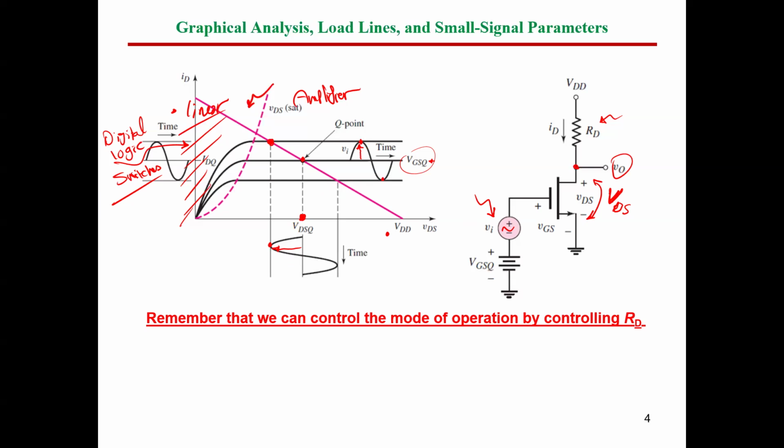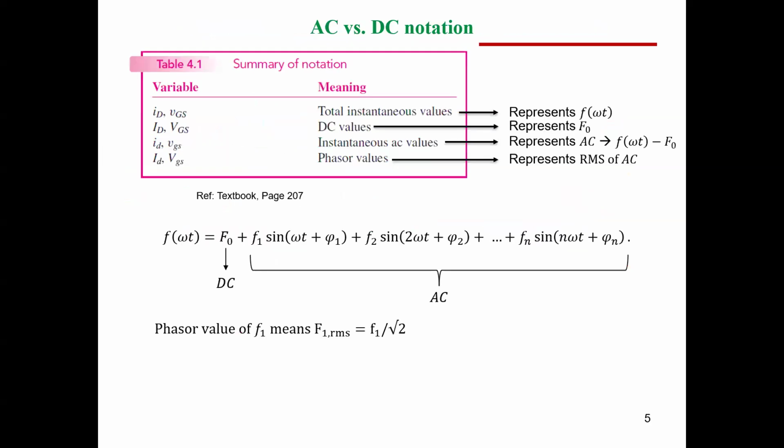So this is the concept of having an amplifier. So firstly, you need to identify the DC analysis in order to provide the DC component or the Q point. Q point means a certain value of ID, a certain value of VDS, and a certain VGSQ. Then applying the AC components according to the gain value we have and the load line, we will provide the output volt here. Okay, so this is the amplification process. Let's go more in depth and see the difference between the analyses.